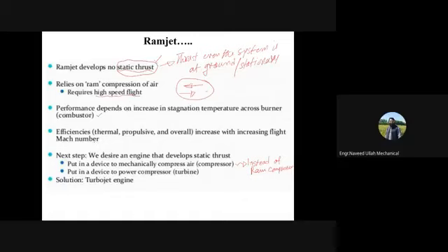That is obvious, that the higher the Mach number you have, say for example 1, it means the air is entering the diffuser section with sonic velocity. Sonic velocity is around 340 meters per second, so it is more than that. If the Mach number is greater than 1 or equal to 2, you can see that the velocity at entrance, or at entry, is increased, and that is converted to pressure. So more pressure ratio will be here, and similarly you can increase the ramjet velocity.